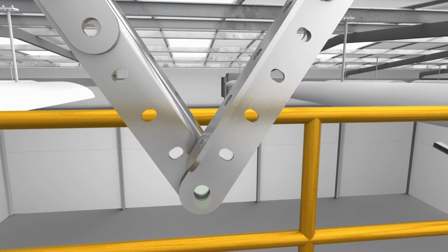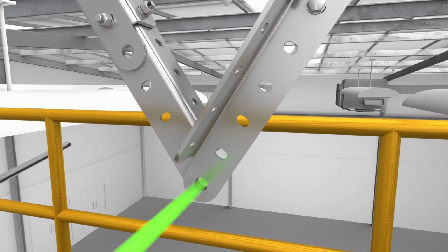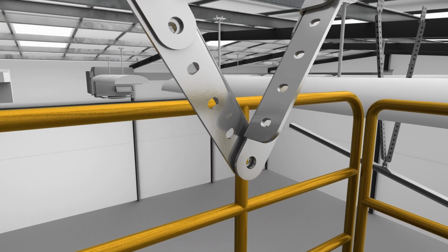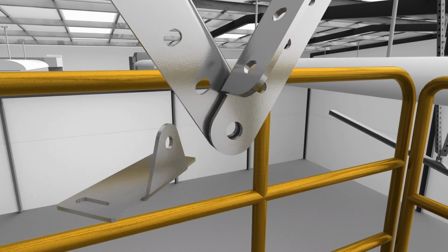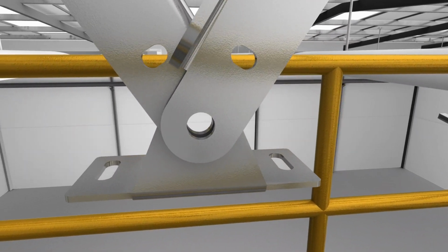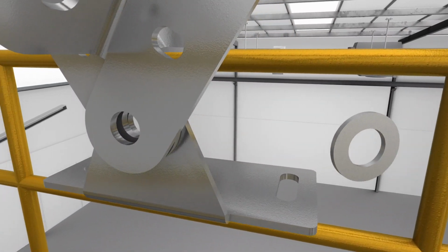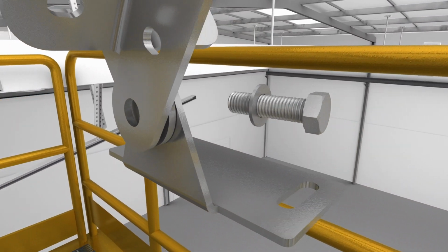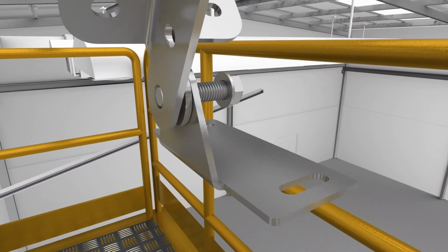This will form the central bolting position onto which the slotted clamshell top brackets attach. Attach one of the slotted clamshell top brackets onto the outside of the hanger link arm assemblies and insert an M16 50mm bolt, ensuring a flat washer is positioned beneath the bolt head.